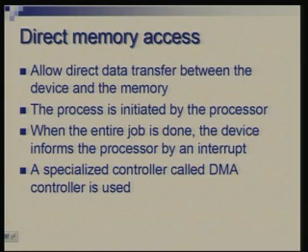For example, if in between you found a bad sector or some error occurred, then status would be set accordingly and the processor interrupted. So, the processor has to see at the end whether the IO operation ended successfully or there was an error. This entire job is entrusted to a special controller, a special piece of hardware called the DMA controller. In the DMA controller you would specify memory addresses, the amount of data to be transferred, the direction of transfer, and what is to be done at the end of the transfer.